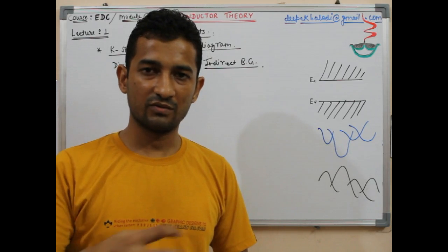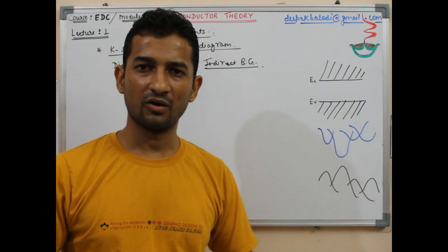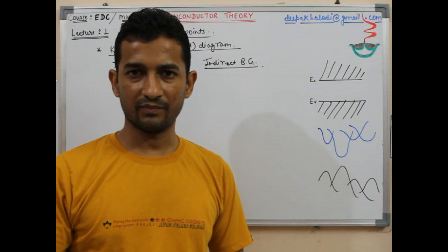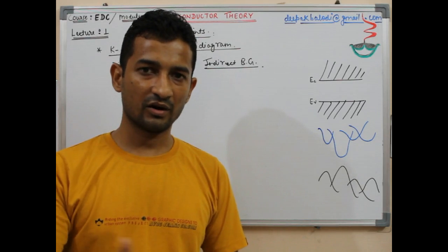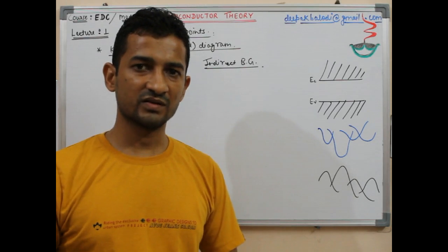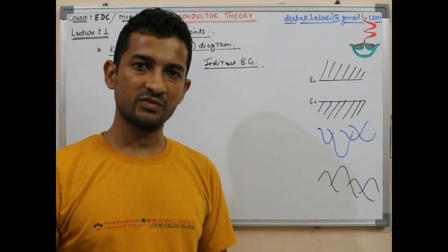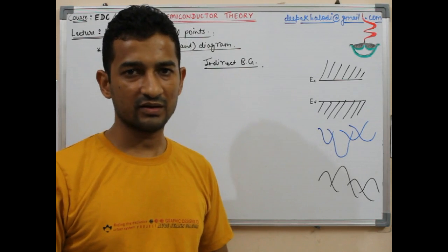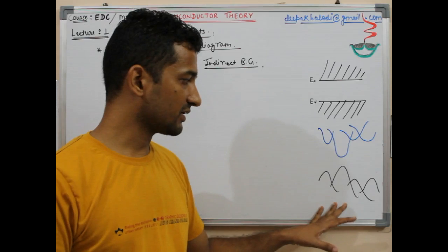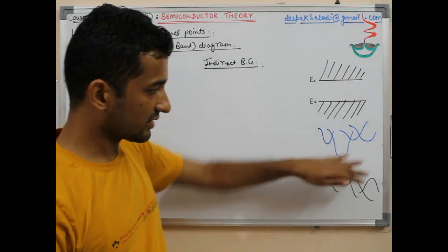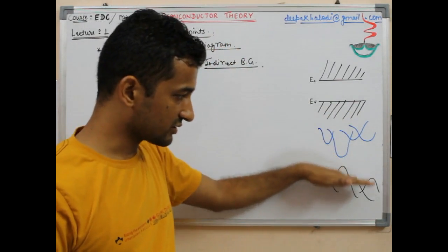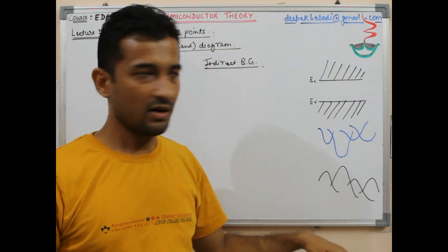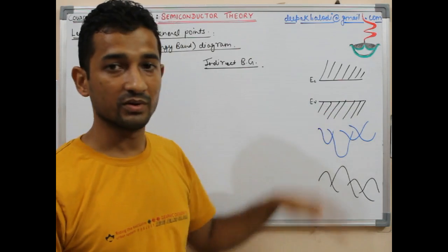Any electron, when it moves within the crystalline material, is governed by lots of energy, experiencing it from the atom itself, from some neighbor electron or hole itself. So its energy profile and its wave vector profile is not so simple, it's highly complicated, and we should understand that this whole blue color and this upper one is the conduction band, and this one is the valence band, and definitely they are not so simple.